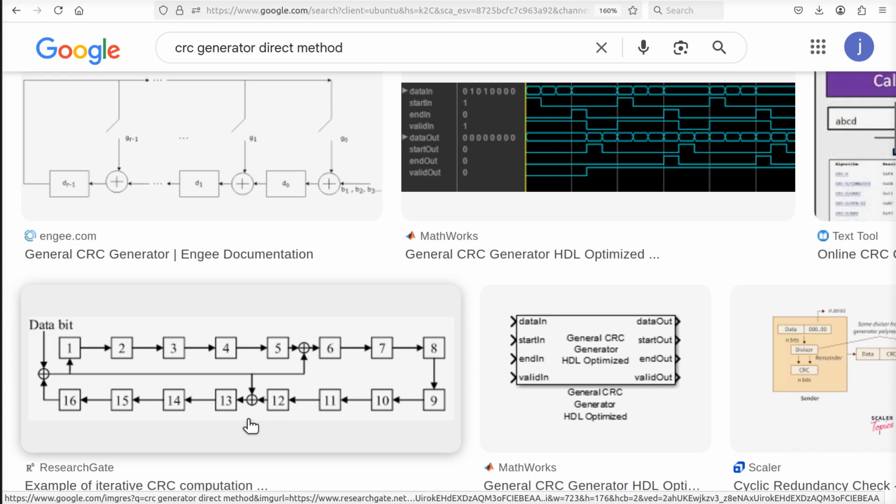So the polynomial for this will have 3 bits set in a 16-bit hex value, or 16-bit binary value, all right? So there'll be the least significant bit here, there will be one here and there. So what will that be? This is like, bit 0 is always going to be an XOR gate, right? So there would be an XOR here if there was a 1. Oh, we got 1, 2, 3, 4. So the polynomial will end in a 1, because there are 4 bits, the least significant 4 bits of the polynomial hex constant, if you express it in hex.